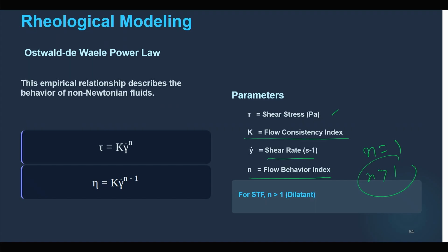After understanding this shear thickening fluid, now how to apply it on fabric. So, the fabrication process: we make a dispersion, the silica is dispersed in polyethylene glycol using ultrasonication to break the agglomeration. So, we do ultrasonication and it will prevent agglomeration.